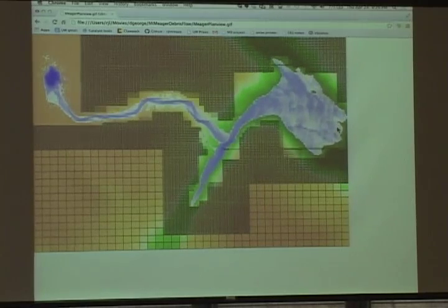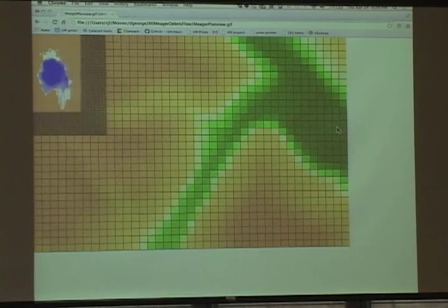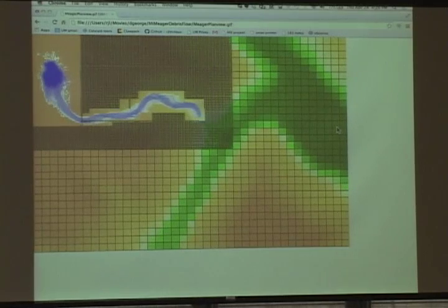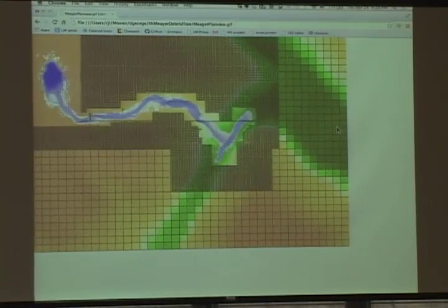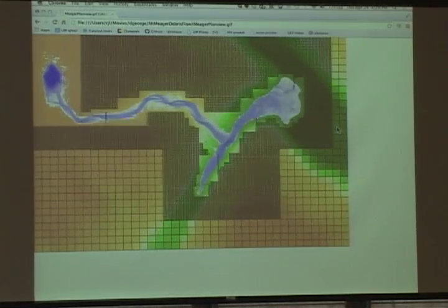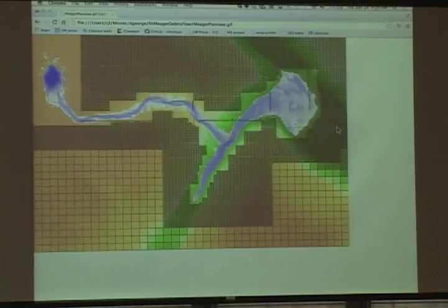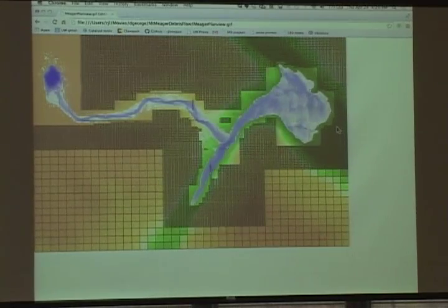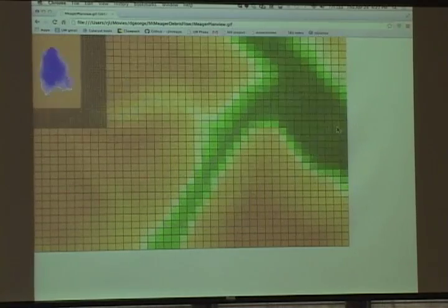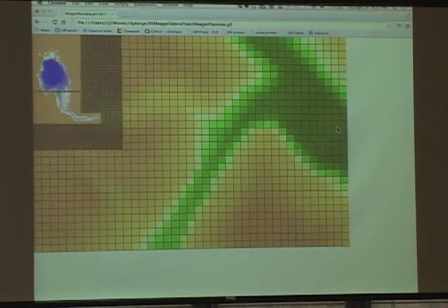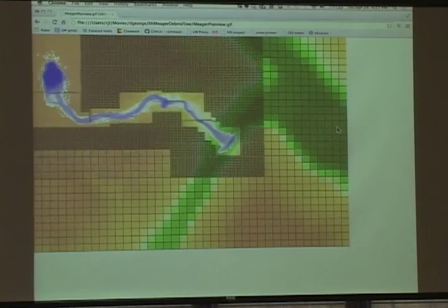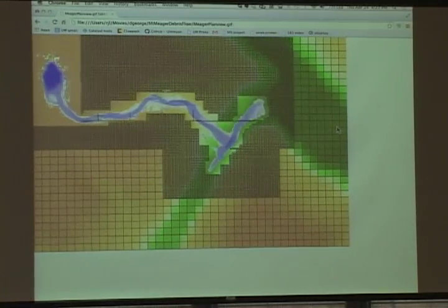And so every few time steps, we do a regridding on every grid level. You flag the points that need refinement according to some criterion, and then those flagged points get clustered into rectangular patches, and you take a few time steps, and then you regrid, and this is done recursively at all levels. So in this particular simulation, they only use 3 levels of refinement, but often for tsunami modeling, I'll show some results later where we use 6 or 7 levels so that you can start with very large grid cells on the ocean and zoom down to very small grid cells, a few meters on the side perhaps, in a particular harbor that you're trying to model.